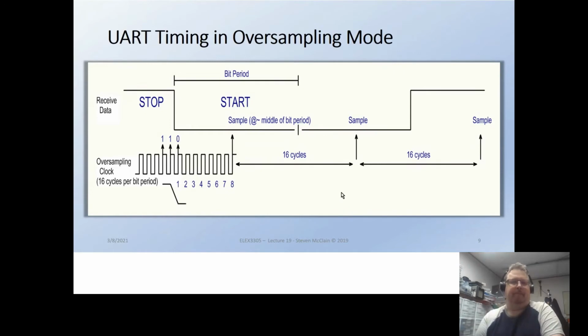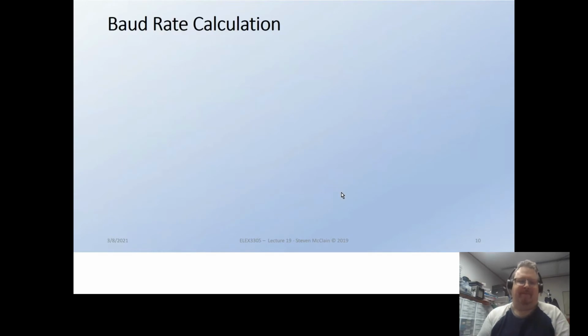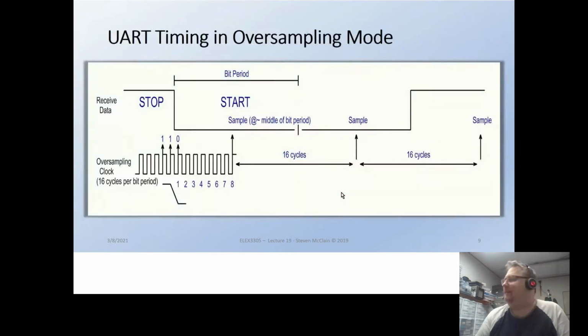Tricky? That's a little bit to grasp. Well, you see the difficulty you'd have trying to synchronize the clock any other way. To actually get those edges to be exactly right, you would have to slow the one down until they're right, and like phase lock loops, or I don't know how much of this stuff you guys have done, but trying to change an oscillator is tricky. Well, this one doesn't actually ever change the oscillator; it just runs at 16 times the speed, and never has to change at all.